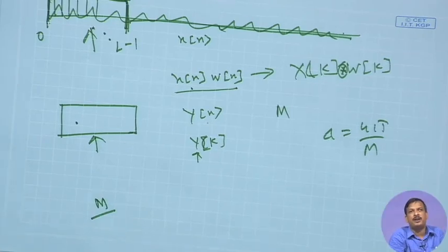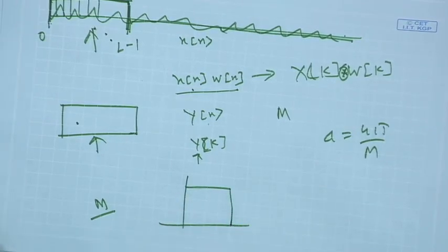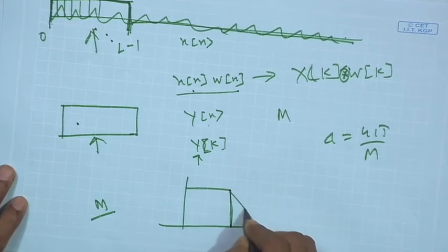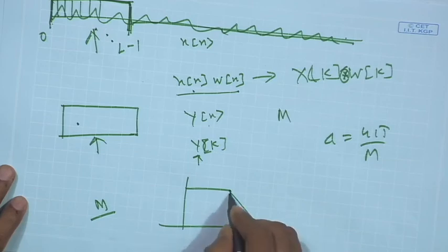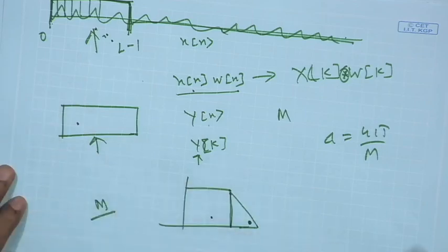If I implement the filter in FIR way, I said finite impulse response. Ideally, a filter has an infinite impulse response, so I truncate the infinite impulse response to a finite number. If it is m, then m is called the order of the filter. Ideally, if I want to design a low pass filter, this is the infinite impulse response. Once I truncate it, I cannot get this sharp cutoff, so I get a transition. This transition bandwidth depends on what kind of window I have used to truncate the filter transfer function or truncate the signal.